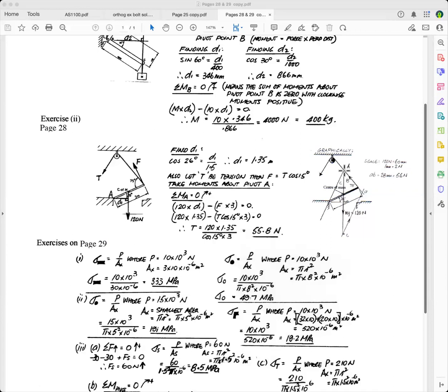And then you just draw that up there. And so you've got the directions, not the sensors, but the directions of the 3 forces that are acting on this trapdoor. So when you've got the 3 forces, they're all concurrent there. And so I just use Bow's notation. So I'll put A all the way around here, because we're not worried about that force up there.